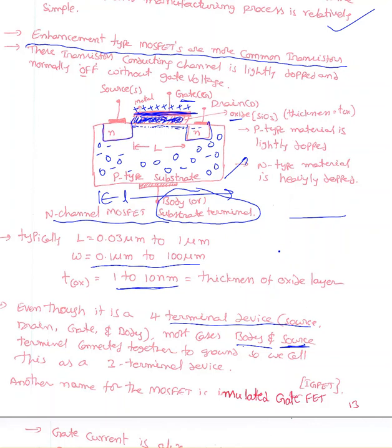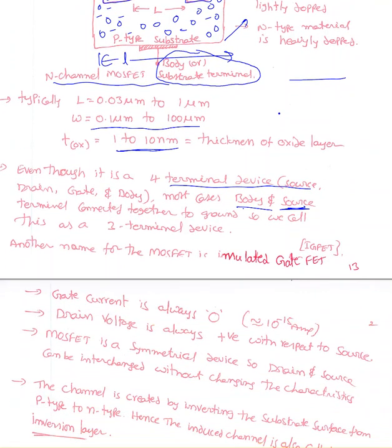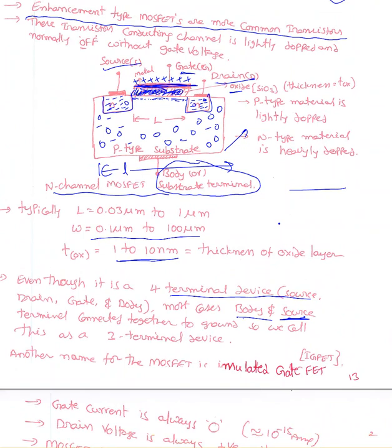So here this is already N-type material. There are lots of free electrons. Majority carriers are electrons, minority carriers are holes. Okay, so whenever we do this, the channel is going to be created. So whenever we supply voltage from drain to source, the current is going to pass from drain to source. Okay, another important thing here, the field is going to be created since we have a positive charge and negative charge. Whenever we separate positive and negative charges, there is always an electric field between these charges.